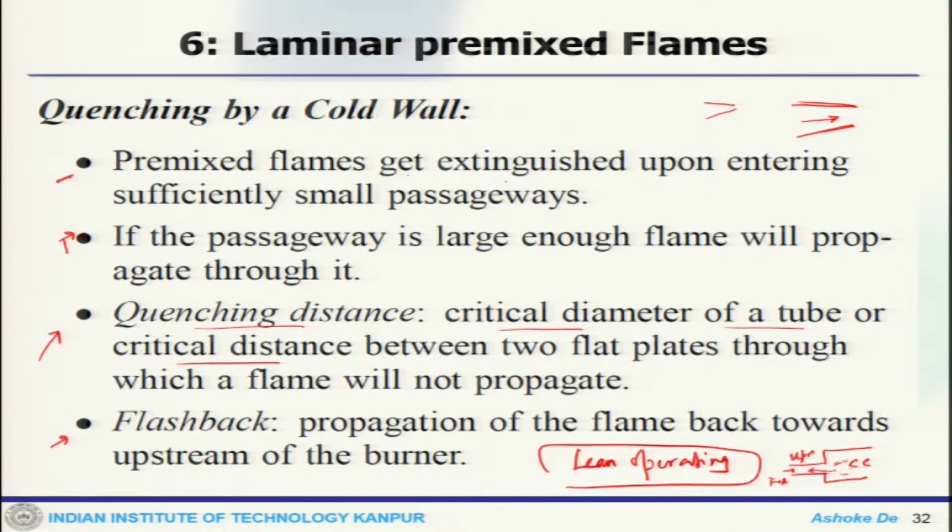Now, does flashback happen all the time? No. It is a very specific situation when flashback happens, when you operate at the lean premix condition. Usually in normal operating conditions flashback does not happen. When you try to operate at the lean premix condition, then flashback is a likely possibility. And why? These are all one after another connecting questions, because flashback happens because of the lean premix condition.